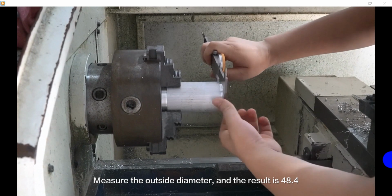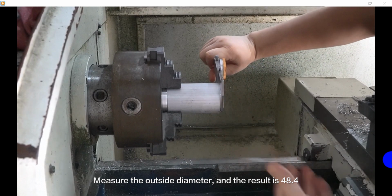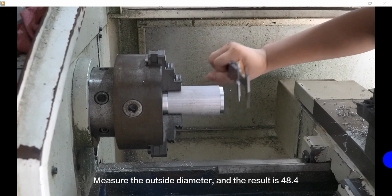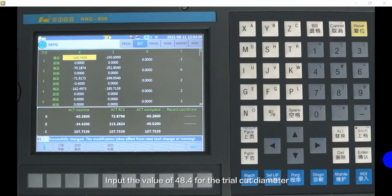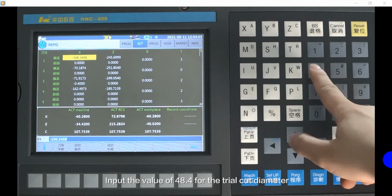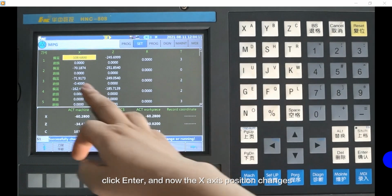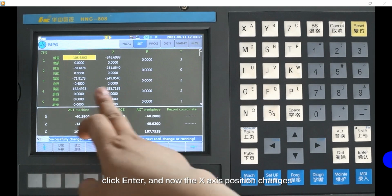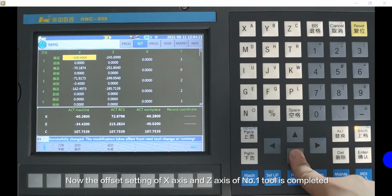Measure the outside diameter of cutting. And the result is 48.4. Enter the value of 48.4 for the trial cutting diameter. And click Enter. And now the X-axis position changes. Now the offset setting of X and Z-axis of number 1 tool is completed.